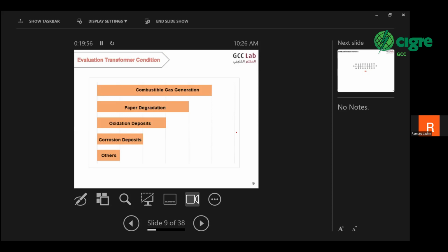Mostly in Europe, I worked in Sweden before, and we do DGA every 6 months. If it is normal, we do it every 6 months. If it is abnormal, maybe every 3 months, something like this.